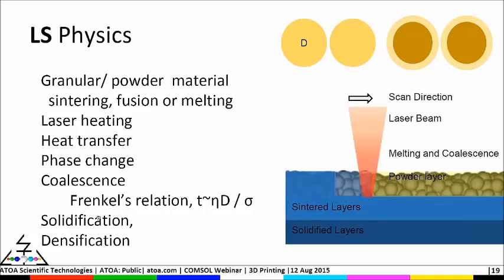And these are the physics involved in this process. As we mentioned earlier: laser heating, heat transfer, phase change, collisions of the particles. In the simplest form, we can relate the collision time T as directly proportional to the viscosity and the diameter of the granular particle, and inversely proportional to the surface tension.